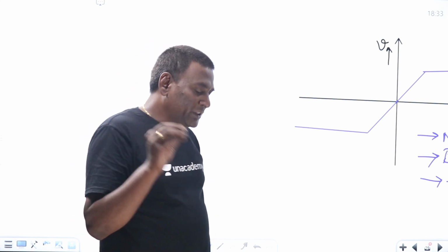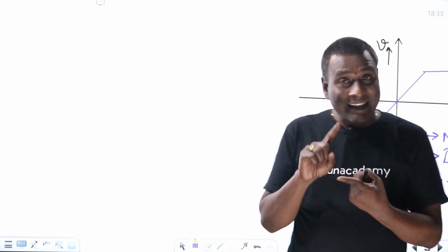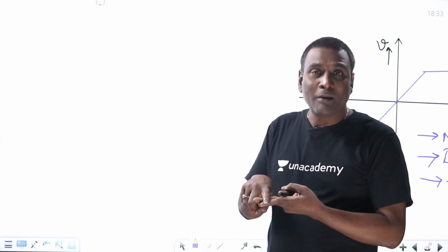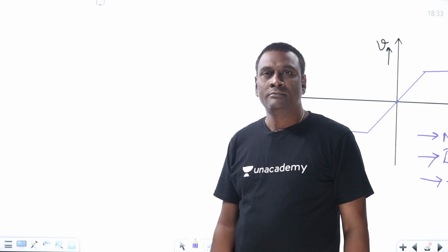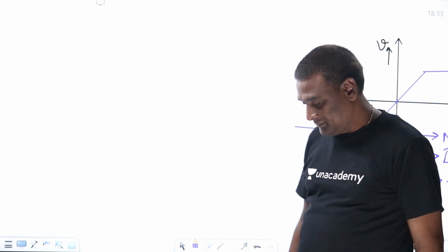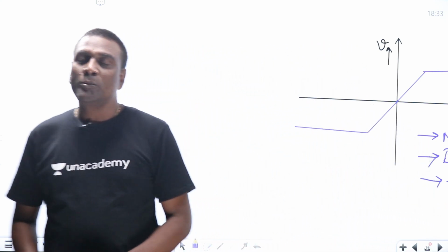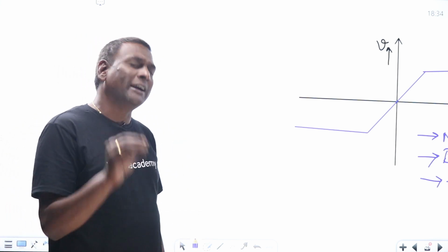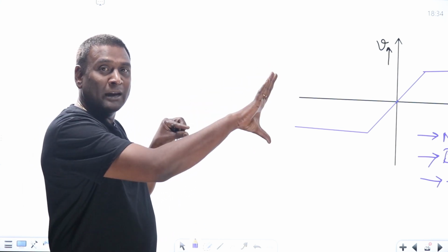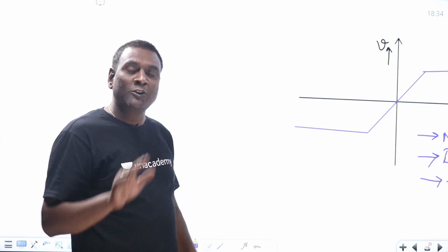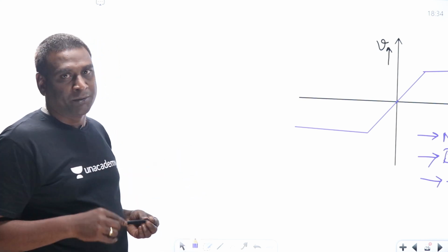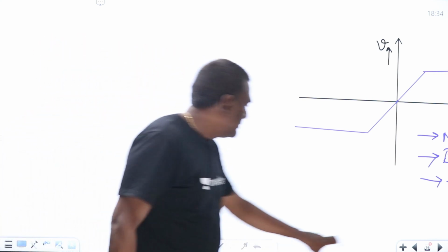So if you think of BJT, if you consider the electrical signal input, then bias power plus signal power is going to be the net output power. But how can you say it is active? By not considering bias power. Whatever may be the power supplied by the biasing circuit, if you neglect it, then the input signal is this much, the output signal is this much. The signal is getting amplified. So we are going to consider them active by not considering the power supplied by the biasing circuit. Anyway, coming to the next thing.